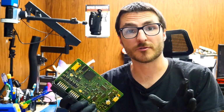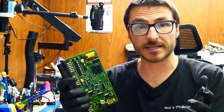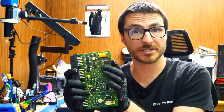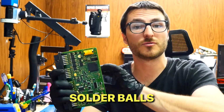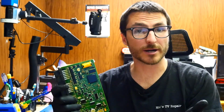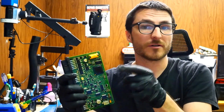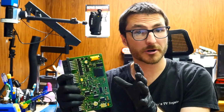Some of the information I've been providing you so far technically isn't true. I've been saying that this processor over here is defective or is faulty, when in fact it's actually in perfect condition and has no problems. The issue is the solder balls that connect it to the circuit board. Over time, those solder balls deteriorate in quality, they develop cracked solder joints, and the data going from the processor to the rest of the circuit board can no longer flow through. So that's what we're going to be repairing today.